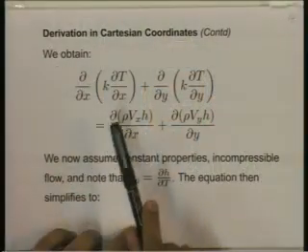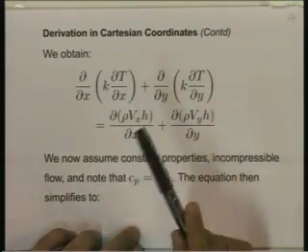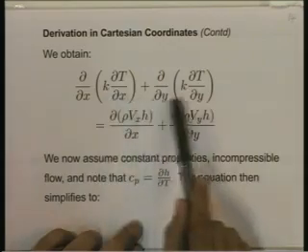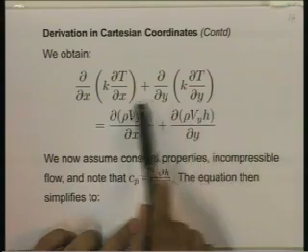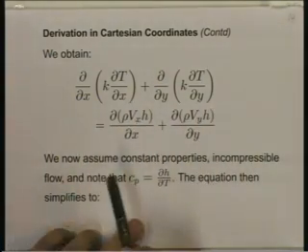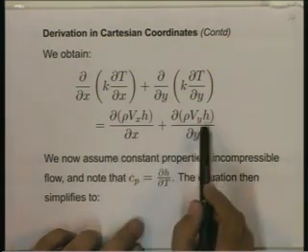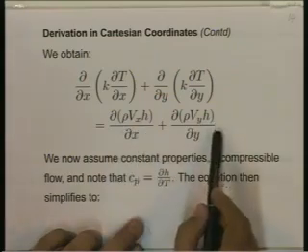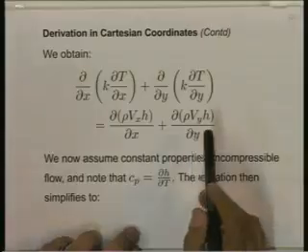On the left hand side of this equation, we have terms containing conductivity and temperature gradients, both in the x direction and y direction. This is the final form of the Q term of our first law of thermodynamics. On the right hand side, we have terms containing Vx, Vy and H. These are the enthalpy outflow terms, the final form in the differential equation of the enthalpy outflow terms.